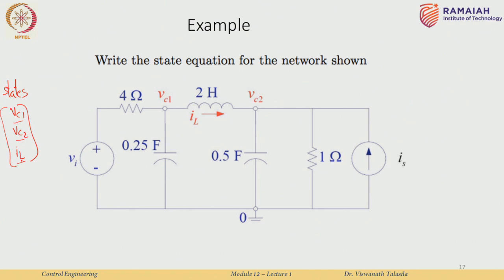So, let us start off and we can analyze this circuit in 2 steps actually. So, the first step is to basically write down the nodal analysis at these 2 particular nodes. So, basically we are going to write the KCL at these 2, and in the second step we are going to apply KVL in this particular loop, alright. So, first let us look at node 1,